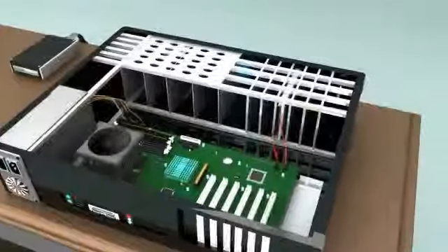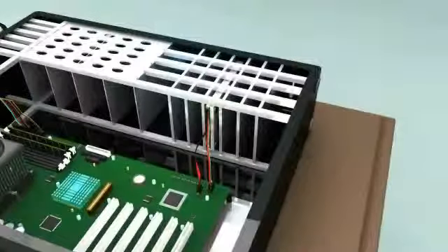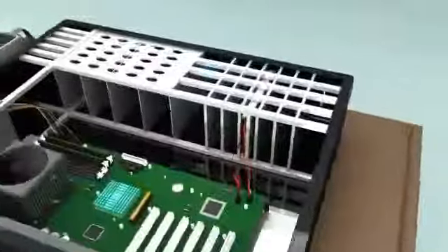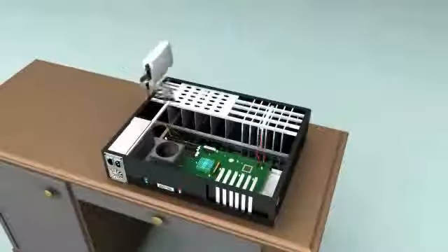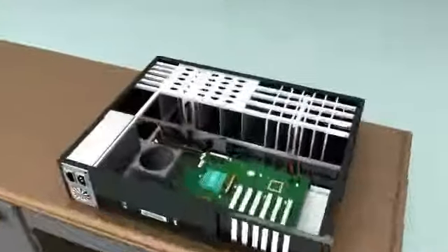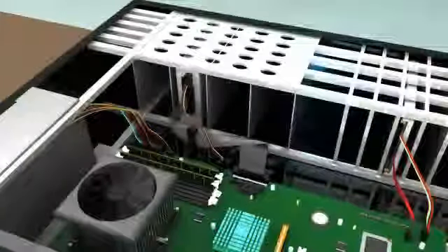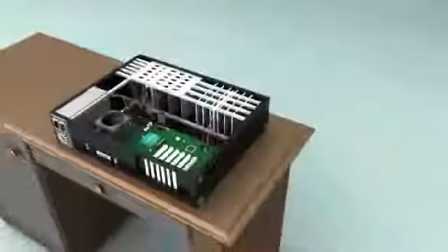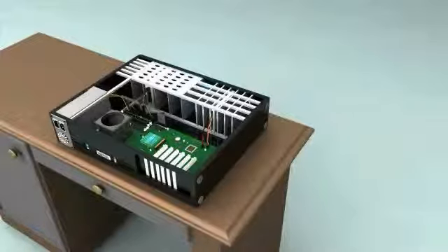Fit the hard disk onto the slot provided in the ATX case and connect the SATA and power cables to the respective pins. Similarly, fit the DVD drive in its respective slot provided in the ATX case and connect the data bus and power cable to the respective pins.